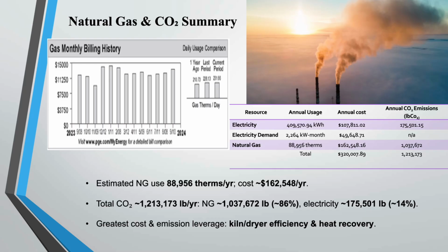The electric side measures still matter as they trim kilowatt hours, reduce demand peak, and deliver incremental CO2 reduction. For checking, we recommend a simple measurement, reporting, and verification plan, which consists of a monthly roll-up of kilowatt-hours and therms, a log of compressor leak and pressure change, and heat exchanger change for exhaust temperature and flow. So we can confirm that savings are persisting. And the bottom line is gas measures deliver big carbon reduction, and compressor air measures deliver quick cash and lower peak. Together, they produce the 8.5% portfolio reduction we showed earlier.